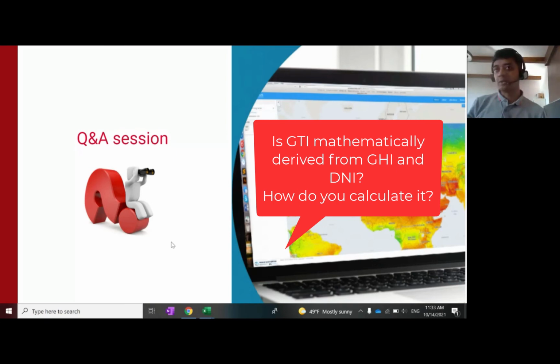And I would say two main reasons for that difference would be a slightly different implementation of the Perez model, and also that we would typically run the calculations in a 15-minute time step, whereas in PVsyst it's done on an hourly time step. So for fixed tilt, maybe not such a huge difference, but for tracking systems, you might see bigger differences, particularly in the early morning and the late afternoon hours.